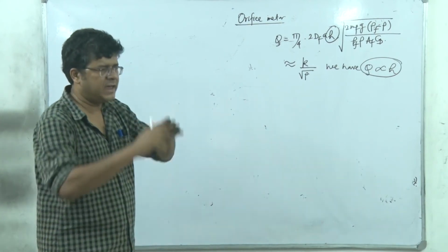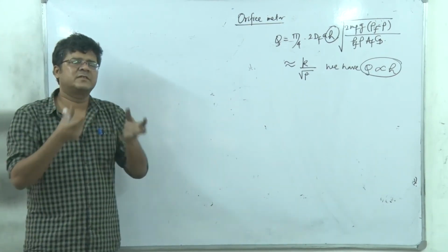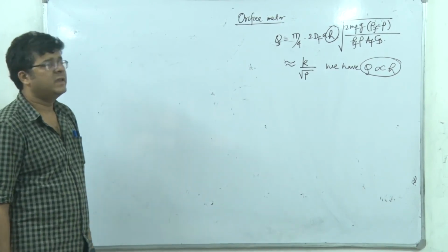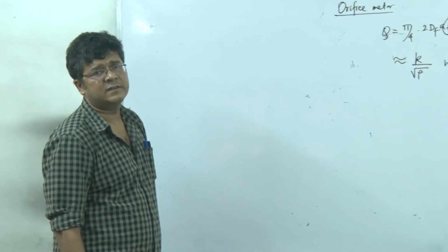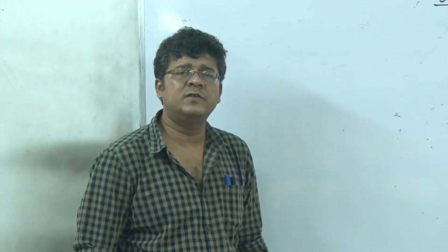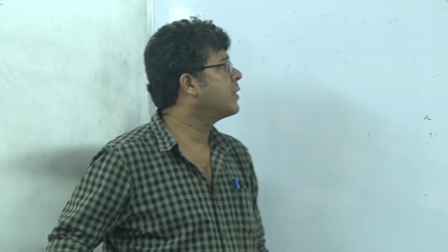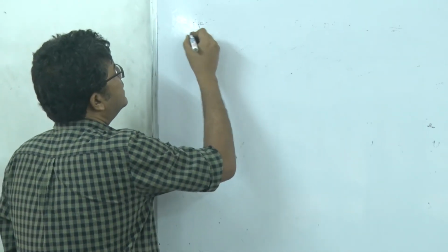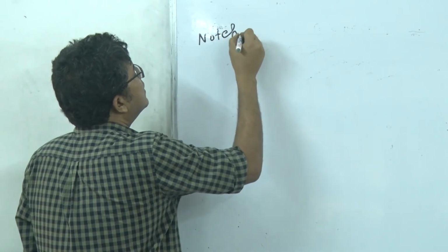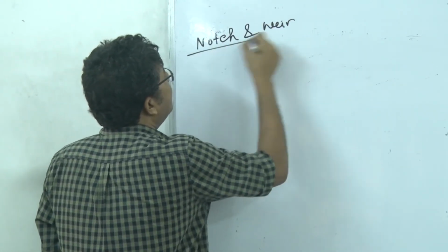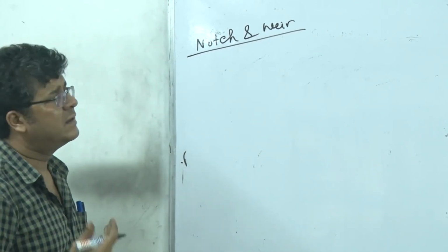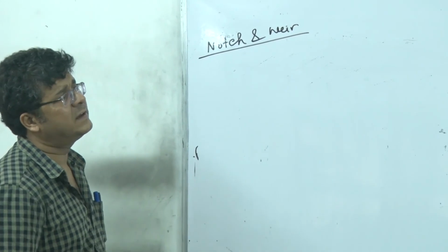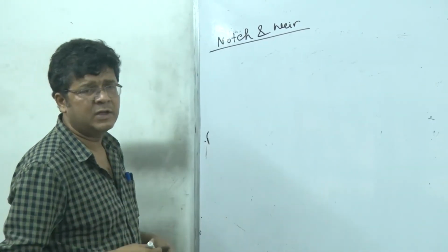Just like if I have an orifice meter and truncate it, it becomes a circular notch or circular weir. Generally, notches are small metallic structures used for measurement of flow in open drains, whereas weirs are large machinery or concrete structures used to determine the flow in canals, rivers, etc. The basic hydrodynamics in both cases is the same. Weirs can be considered a scaled up version of the same notch, right?